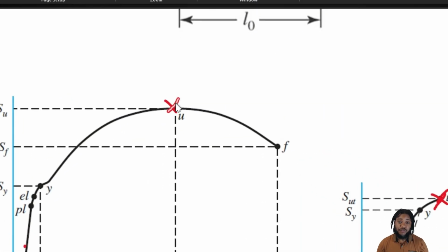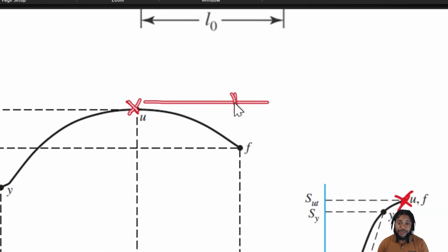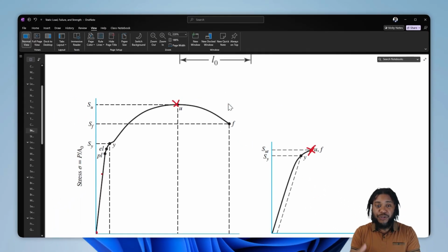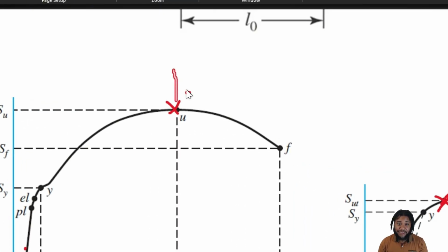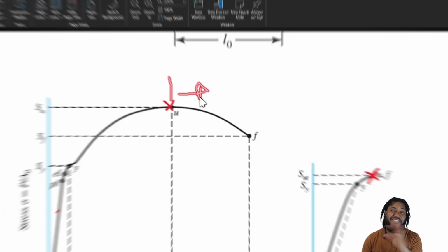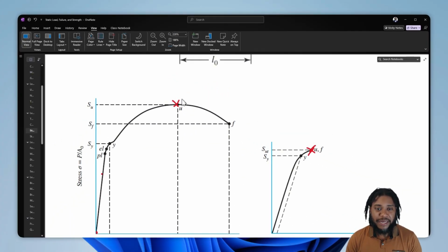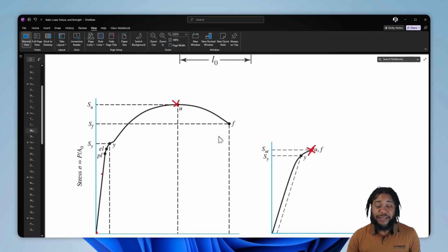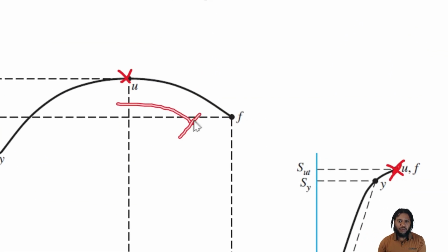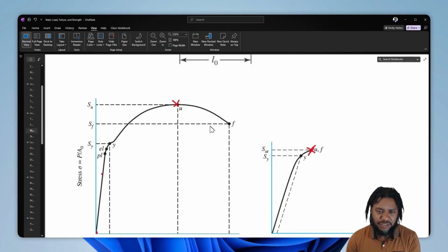Now, with ductile materials, once we reach the UTS, beyond that point, our part starts to neck down. So the cross-sectional area starts to decrease. The maximum load stress we can sustain decreases, and then we get fracture. Generally, when we're designing a part, if we get past this point, it's failed. The part is done. But because of that additional ductility, we have at least some awareness that our part will fail. We have awareness that our part has exhausted itself. It has permanent deformation in its shape. This doesn't look right. We need to replace a part.